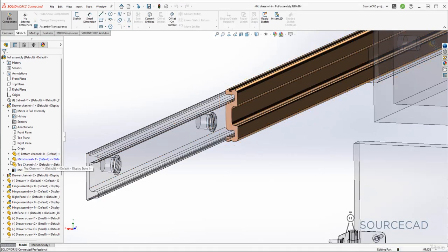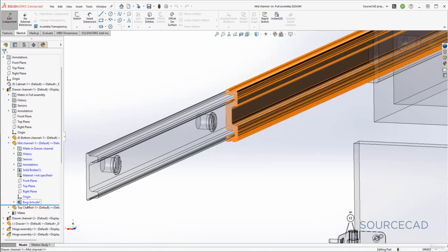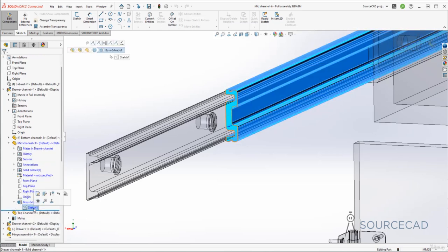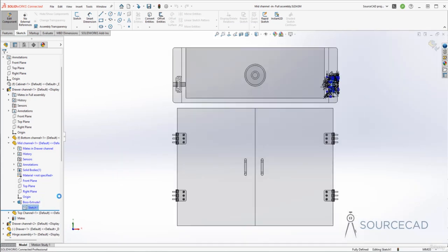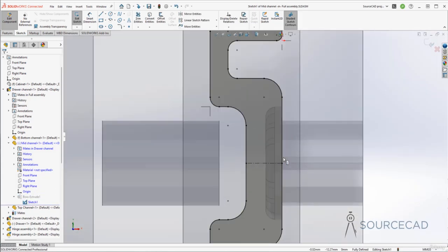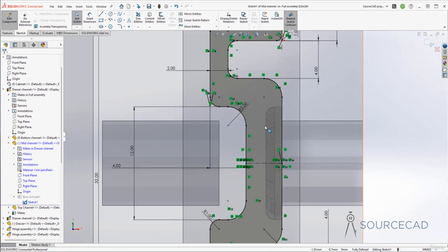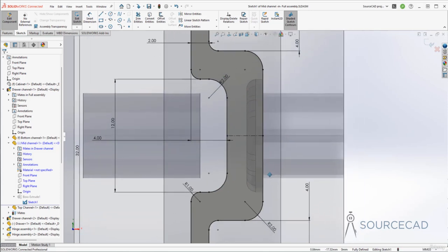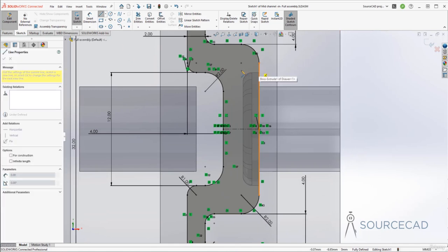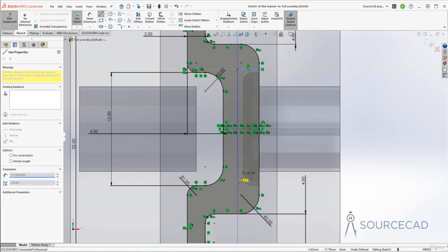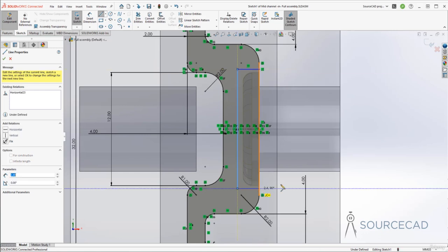All right, so let's just go to this mid channel and we have the boss extrude feature right here and the sketch right here. We just want to modify the sketch. So I'll go to edit sketch, which is right here, and let's just modify it. Now you can see this screw in the background and you can use it as a reference. So I'll go to this line tool and I'll make it just like this. So maybe this, and I'll join it with this.